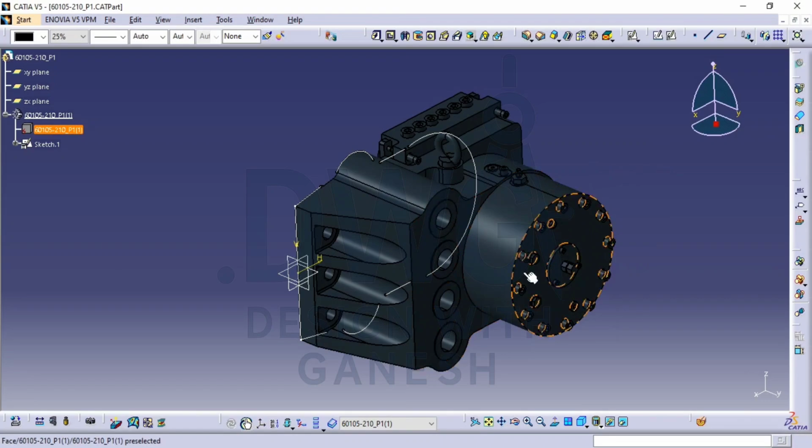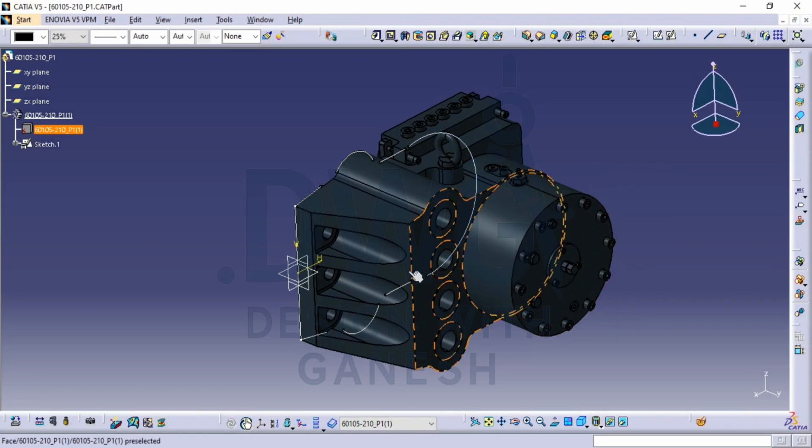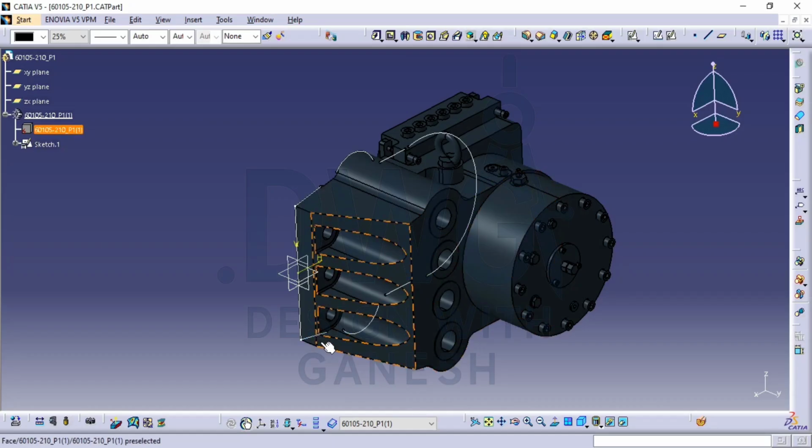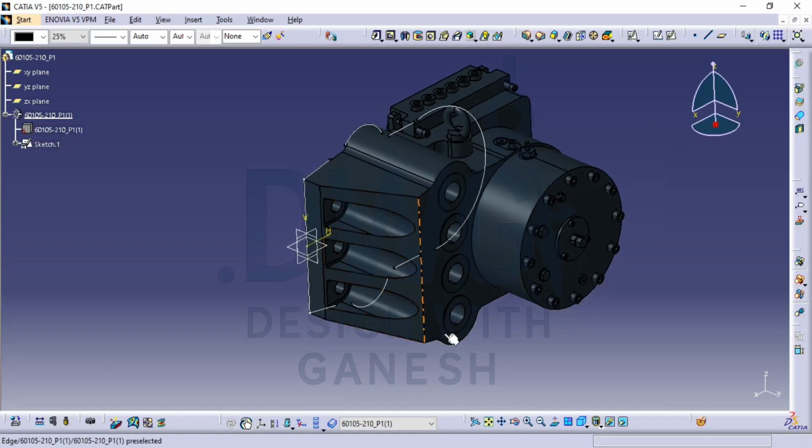See, in the remastering process, you have to take the references of this 3D model, but you are not maintaining the dependencies. What exactly does dependency mean? You projected this line based on this geometry, right? So that means the line has a relation with this geometry.